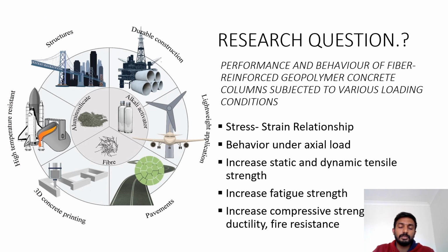Moving on to the research question: the performance and behavior of fiber reinforced geopolymer concrete subject to various load conditions. The stress-strain relationship, behavior under various load conditions, increasing the static and dynamic tensile strength, increasing the fatigue, increasing the ductility, the compressive strength, and fire resistance are also being studied.